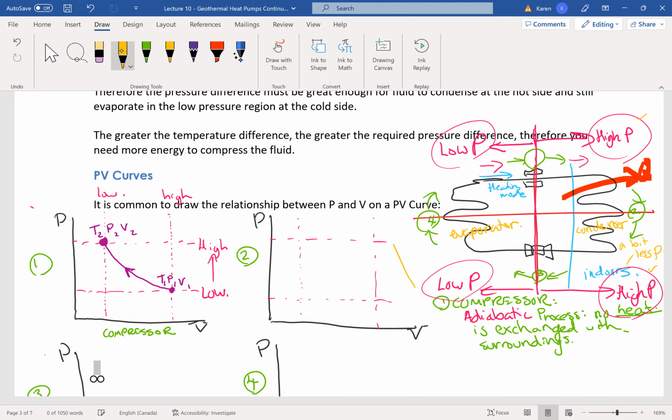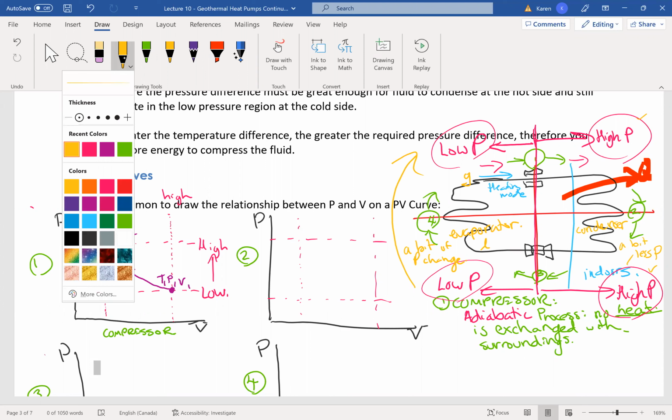So again, I'm full of lies here too, because as you go through the evaporator, you have liquid turning to gas. Gas takes up more space than liquid, and you haven't given it any more space. So a bit of pressure change. Okay, I hope that me messing that up and lying about it will stick in your head so that when you're on the final exam, you really remember that because you were told one thing and then another. Okay, so here we go.